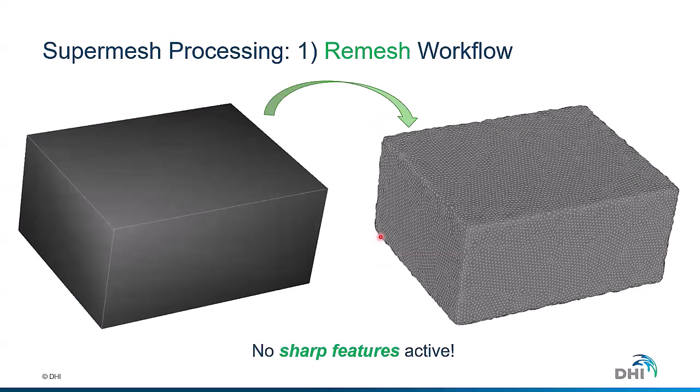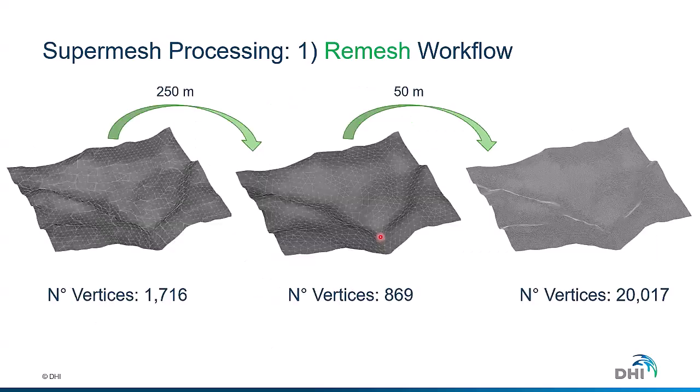Surfaces, so when we start implementing this workflow, we allow the user the possibility to control what information is relevant to keep in the surface. And for this, we use an angle as a criterion. It's called the sharp angle, and this angle could preserve different surfaces. The stricter you are with this preservation, the fewer degrees of freedom you provide to the remesh workflow, and therefore you might not have the best quality.